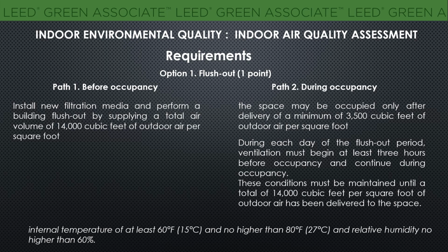In both part 1 and part 2, we have to maintain some criteria like temperature, humidity, etc. So in both situations, the internal temperature should be no lower than 60 degrees Fahrenheit, that is 15 degrees Celsius, and no higher than 80 degrees Fahrenheit, that is 27 degrees Celsius, and relative humidity not higher than 60%.